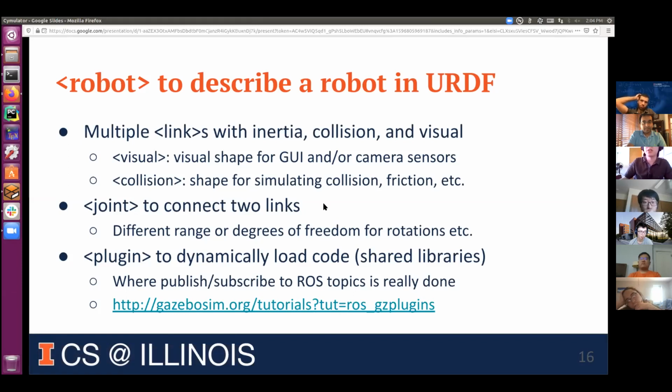They have predefined topics, for example, starting from the position, and there are even ones for differential drive and Ackermann, with some plugins that support, for example, Ackermann drive messages. But basically, it's very specific to each plugin, and if you are debugging, you need to really look into it.